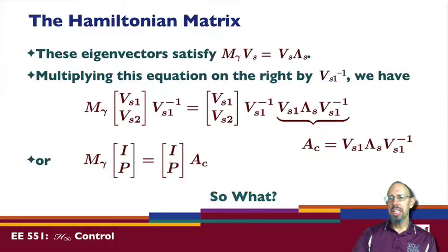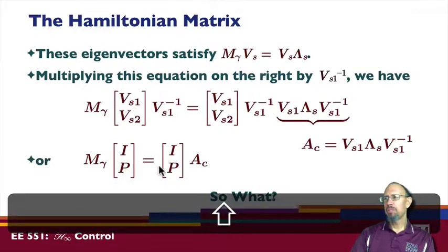And what exactly does it mean? Well, it refers to the fact that we have an intertwining relationship, or an invariant subspace. When we talked about invariant subspaces, we saw something like this before. In this case, it's clear that the invariant subspace is such that A_c has eigenvalues that are eigenvalues of M_gamma, and in fact they're the eigenvalues associated with lambda_s. They're stable eigenvalues. So in a sense, this is picking off the stable eigenspace. This is another set of basis vectors for the stable eigenspace. It's just a different set of coordinates.